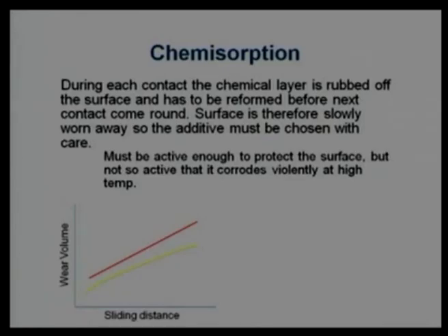It is not as linear as Archard's law states. You can see here that wear rate and wear volume are lesser compared to the dry case, but it has a non-linear profile. This gap may increase or decrease, depending on how fast the distance has been traveled. If it is very fast, there is a possibility it goes down, it goes up also.